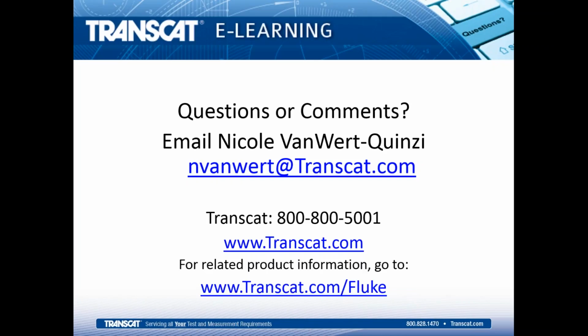So you want to follow the manufacturer recommendations, but maybe you have a special requirement where you're trying to have more accuracy than is specified for just an arbitrary 1-year period, for example. It's possible to calibrate them every 90 days in some cases in order to make sure that they're staying in, or another option is to continuously check them at an ice point or in a triple point of water cell to determine whether it looks like it's still in tolerance or not before going through the extra expense of doing a calibration. But typically it's about once every 12 months.